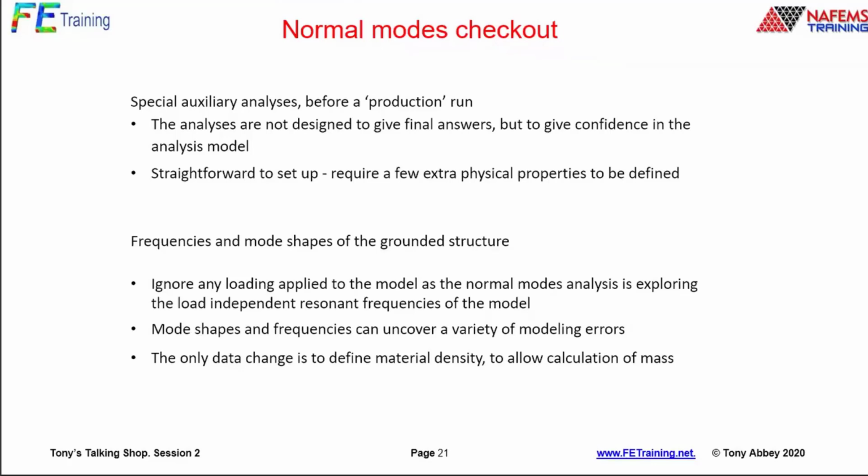So I'm going to add this in. It's such a powerful tool. It's a special analysis we do before a production run. Again, it's not designed to give any final answers. It's nothing perhaps to do with the analysis, but it's going to give us confidence in the results. Now, a normal modes analysis is very easy to set up. The only thing we need to make sure is we've got density on our material properties. As I mentioned before, then we get a mass matrix that goes with our stiffness matrix.